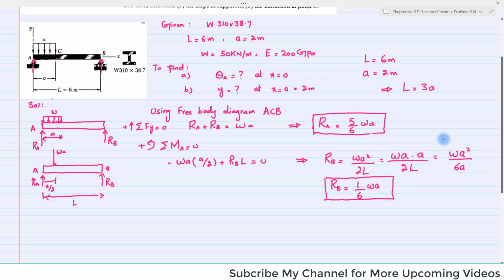Next step will be that in order to find slope and deflection, we will take a section of the beam at this point, and again at this point as well. This is section 1 and this is section 2, because we have been asked to find the slope at point A and deflection at point C.